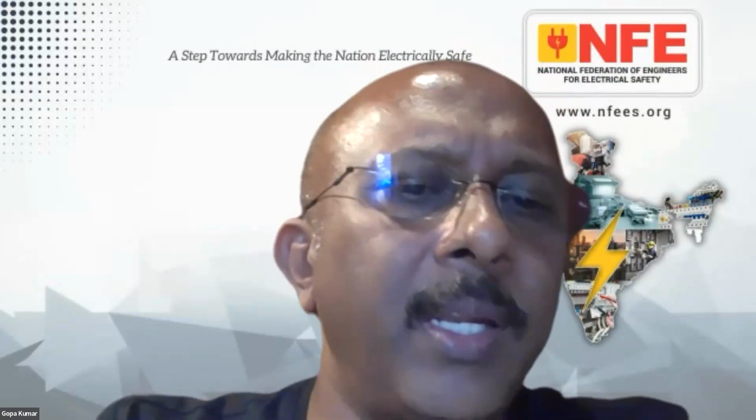Yes, Gopaji, good evening. My colleague has asked a good number of questions from you already. So there is one question. Just as you have explained, till point of supply for distribution, this fault loop impedance measurement and retention of records is mandatory. But what I am given to understand is that for the customer, it is not mandatory and it is kind of a choice given to them, but it is recommended, right? Can you repeat the question? For the customer, it's not mandatory. I don't understand that. For customer installation, customer side wiring, etc., it is mandatory that they perform this fault loop impedance, prospective fault current measurements, everything.